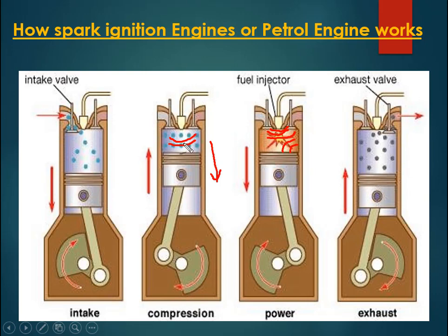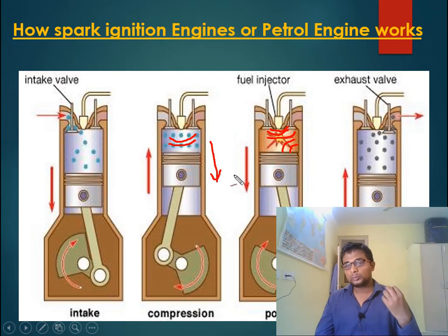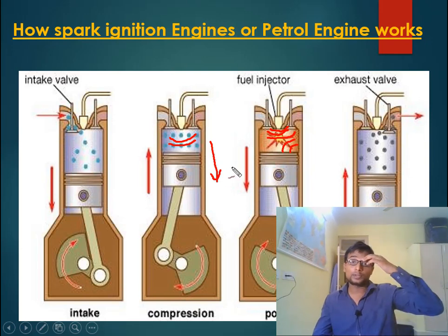This is very detrimental to the engine because the engine is trying to move in this direction, and the pressure wave front is trying to move in the opposite direction, so the engine may be damaged in extreme conditions. So this is unavoidable. Knocking should not take place. Let us understand when knocking will take place, I mean, what goes wrong when knocking takes place.